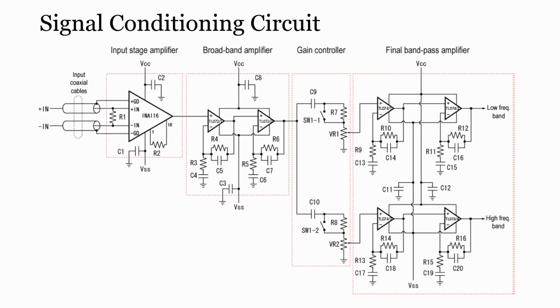In order to understand the functionality of an instrumentation amplifier, we can construct one using normal operational amplifiers. Most of these are 3 op amp based instrumentation amplifiers, where the first two op amps are used to provide the gain to the instrumentation amplifier, whereas the third op amp measures the difference between both the outputs. So, let me draw the 3 op amp instrumentation amplifier configuration.